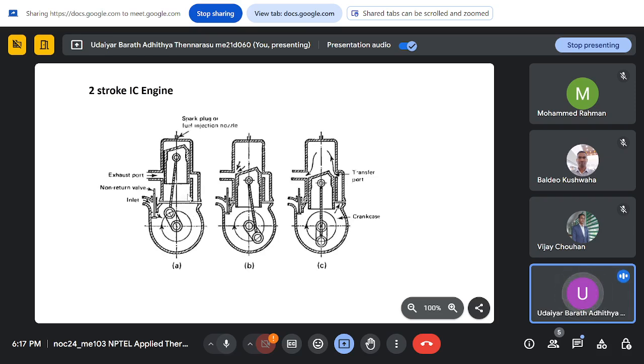When the piston moves down, an opening at the top is now open. The exhaust gas would have all left, and the inlet gas goes back and fills the cylinder, and then the piston starts moving up. It compresses, the spark plug fires, and combustion starts pushing the piston down. So what happened in two revolutions now happens in a single revolution in a two-stroke engine.